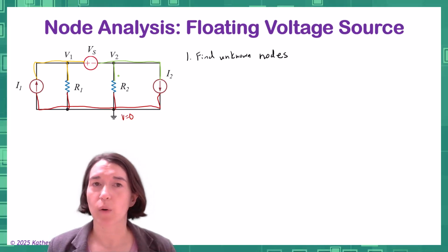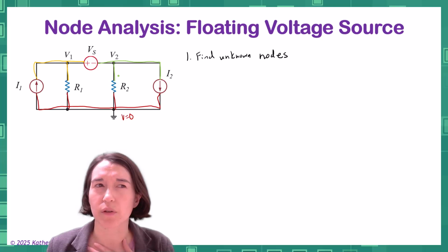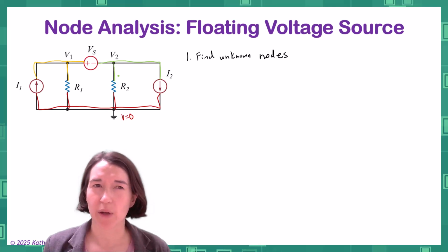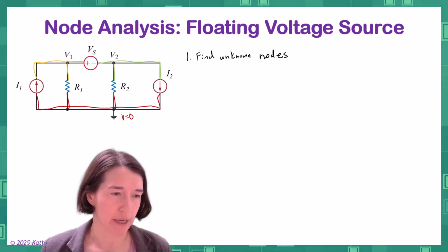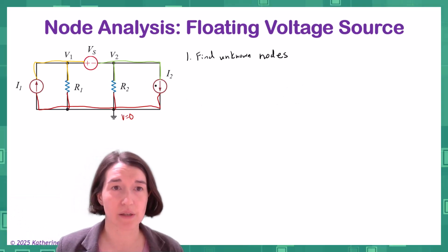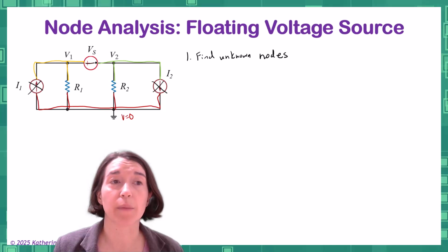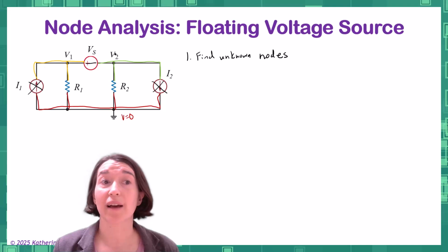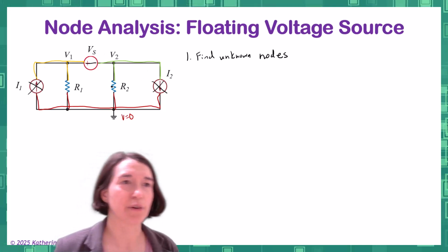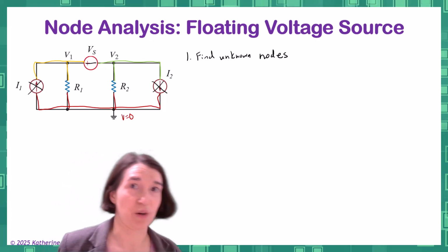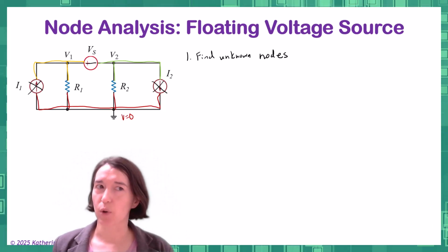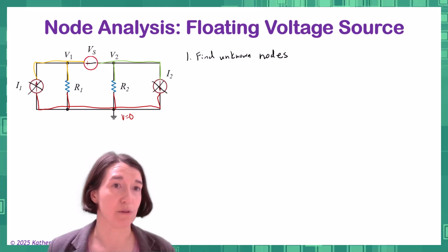So you might say, well, what about the voltage sources? Can't we suppress those, or don't we know them? Okay, well, let's suppress them real quick. We know that if we suppress the current sources, these will become opens, and if we suppress the voltage source, it will become a short. And so actually, we would just have one unknown, right? If we know V1, we actually know V2. If we know V2, we know V1. So we're only going to have one unknown here in terms of voltages.